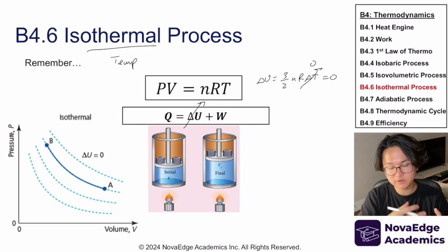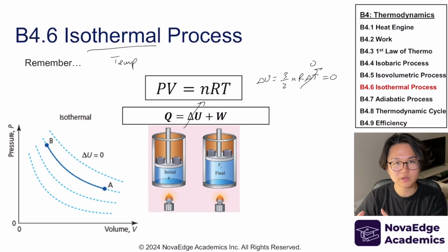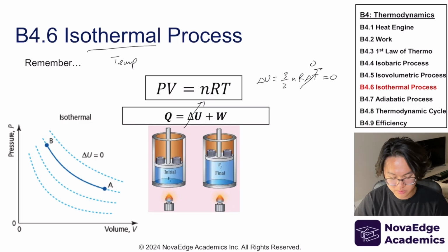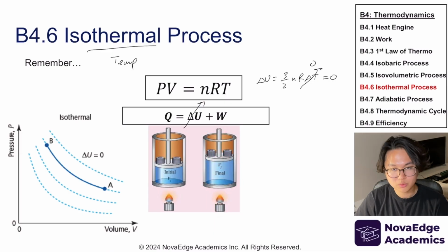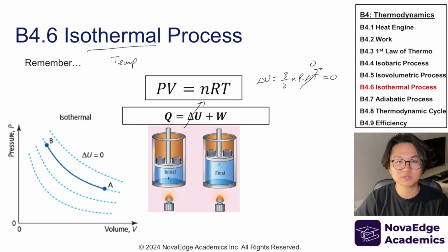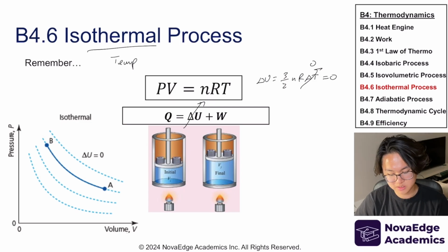So if all of that heat is going into useful dynamic work, this must be the best case scenario, and it really is. But let me tell you that this doesn't really happen in the real world, because for you to put heat in and expand this without changing the temperature of the gas, quite impossible. In fact, you'd have to do it at a very slow and controlled pace at an infinite time, in fact. So this is an idealized case that you'll only be able to do mathematical calculations and be tested on in the exam.